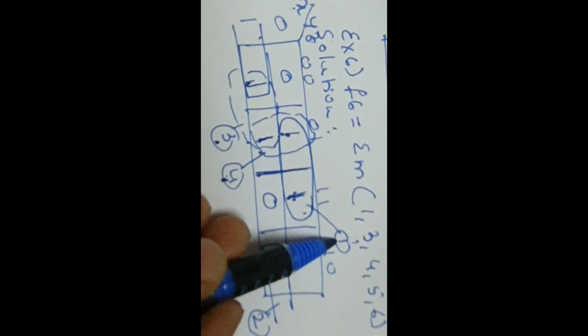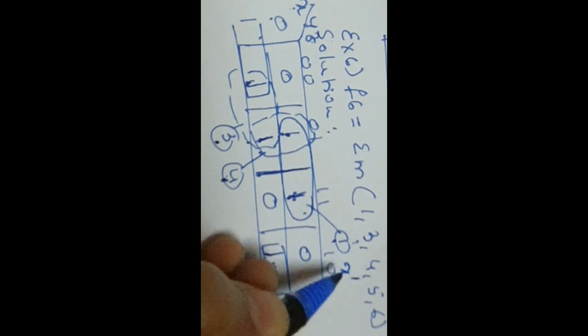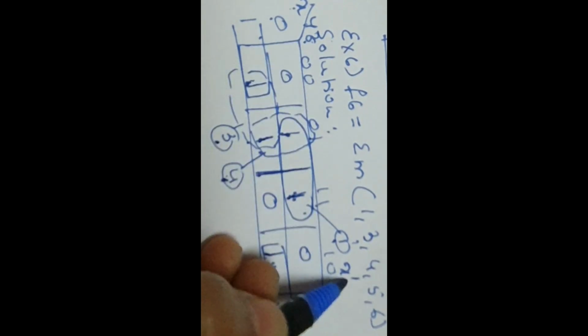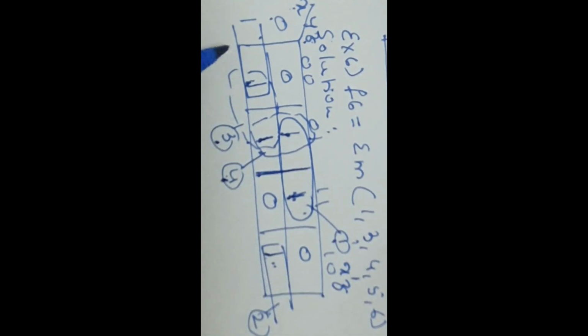Okay. With respect to group 1, what can we write here? Prime implicant, these two. Here x is 0, so x dash is common. These two ones fall in these columns. 0, 1 is there, 1, 1 is there. This 1 is common. This 1 corresponds to z. So it is x dash z. Then this is a prime implicant, an essential prime implicant, because this 1 is covered only in this group.